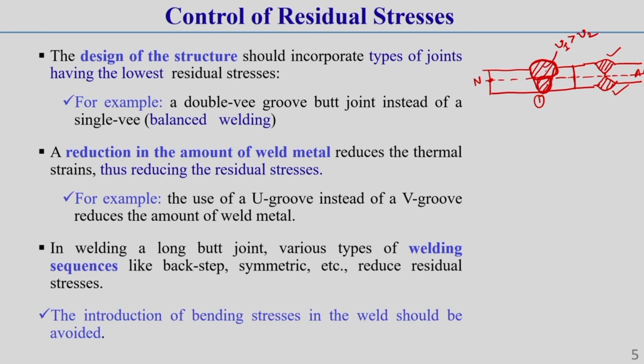So, once sinkage is developed during cooling, as the volume of material at the top side is more, the top sinkage force will be more, but below this neutral axis as the volume of material is less, let the bottom sinkage force be F2. As the volume of material at the top side is higher, F1 is much higher than F2.